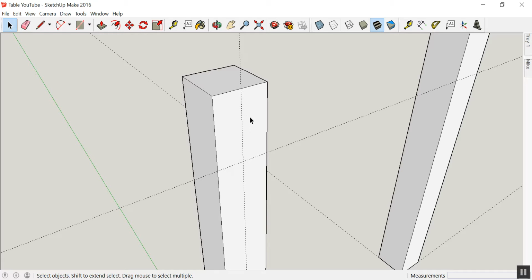So now I have a nice rectangle for me. Now if I hit the R, or if I go up here and grab the rectangle tool, I'm going to type in R, I'm going to go to the corner, I'm going to make sure I'm at the intersection. You can see intersection pop up. Now I click and drag, and when I take it down to that one where it also says intersection, if I look down in the lower right corner, I see 1.5 by 4, which is the size of the rail that I want. I click to say, okay, that's good.